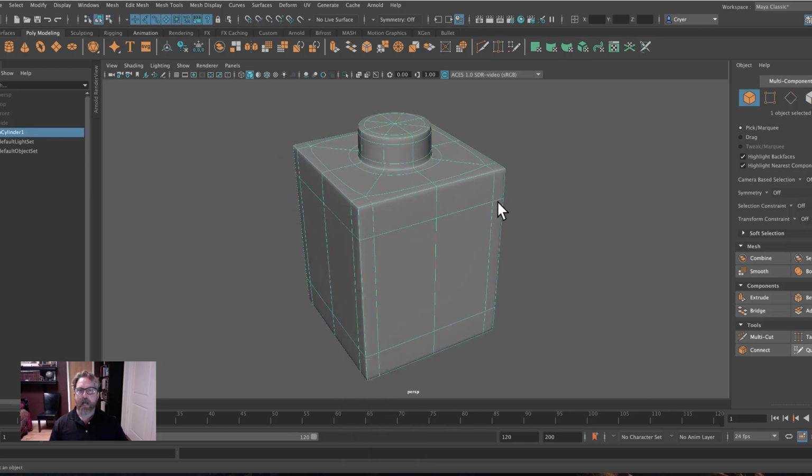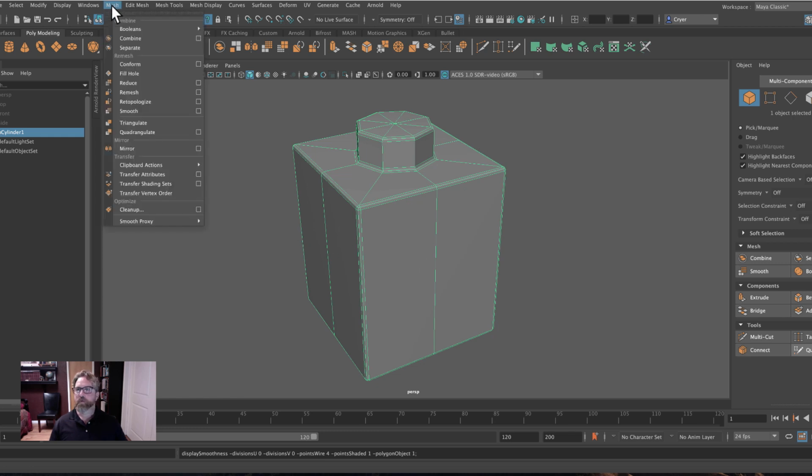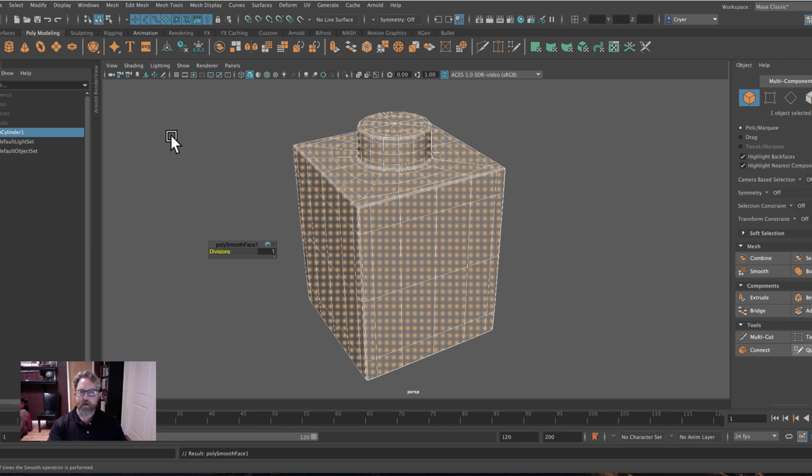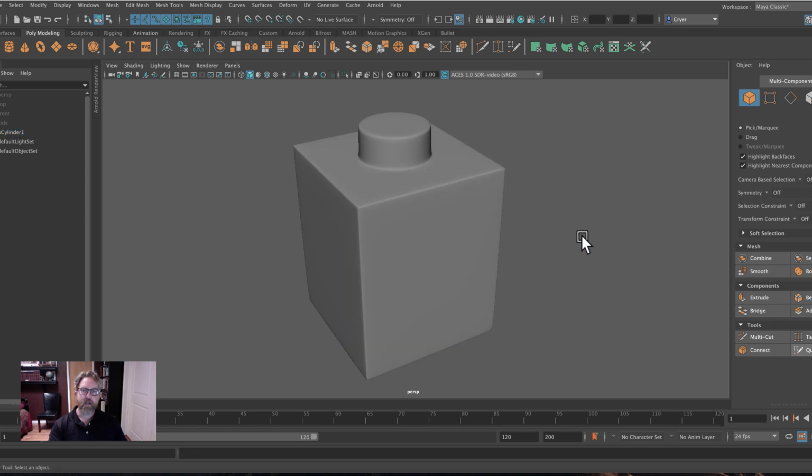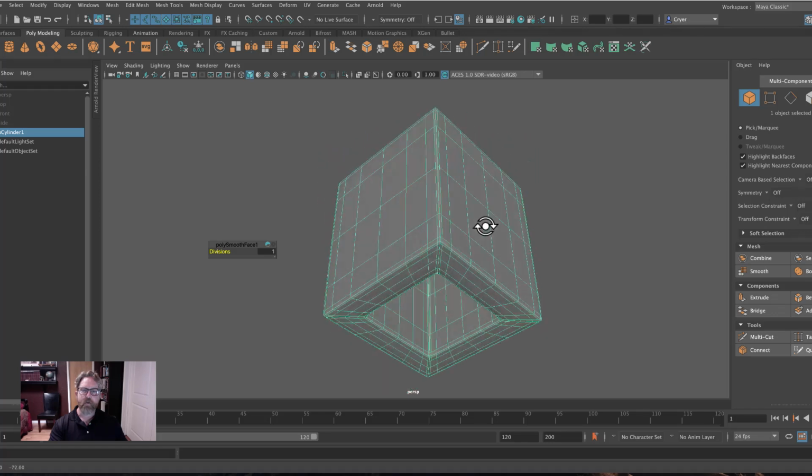And we'll actually subdivide this. Now you would want to save. It's always a good idea to save at every increment, so we might want to come back to this for some reason. So before you subdivide a shape, that is mesh smooth here, and smooth means that we're subdividing it, we're doubling everything, you want to save a version before you subdivide or smooth. But I'm going to execute it here, mesh smooth, and there is what it looks like, and we can even hit the 3 from here and get a nice good view of that